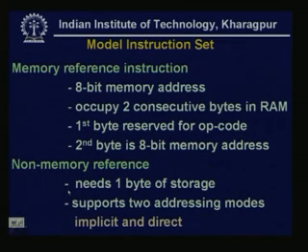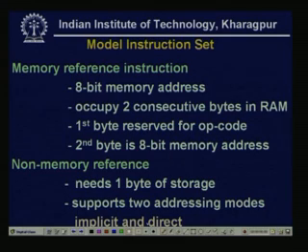The memory reference instructions are those that need a memory address. In this example, we have assumed an 8-bit memory address. The memory reference instruction occupies 2 consecutive bytes in RAM. The first byte is reserved for the opcode and the second byte is the 8-bit memory address.